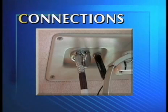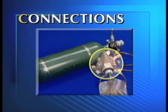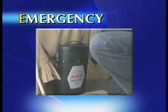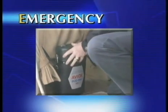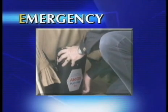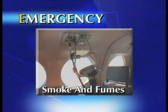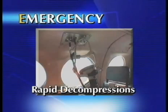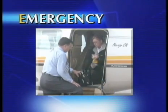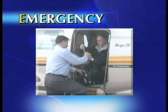Connections. Ensure that all connections are secured. This includes oxygen lines, plug-in coupling, and the mask. Emergency. Have oxygen equipment in the aircraft ready to use for those emergencies that call for oxygen: hypoxia, decompression sickness, smoke and fumes, and rapid decompressions. This step should include briefing passengers on oxygen location and proper use.